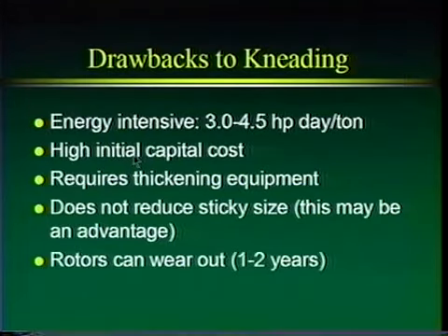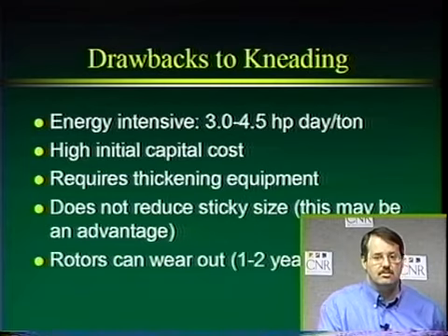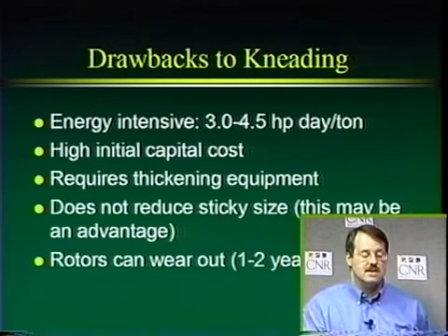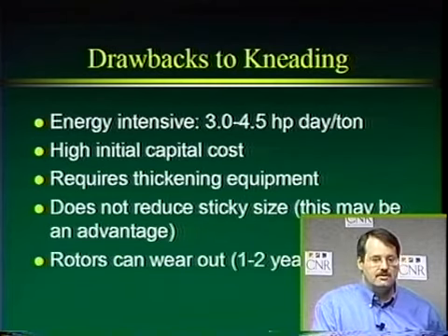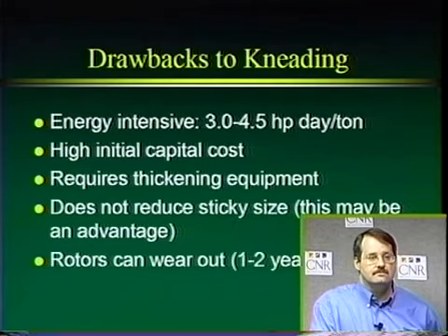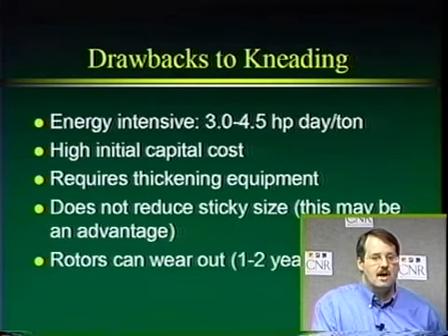Okay, so some drawbacks to kneading. It's pretty energy intensive, 3 to 4.5 horsepower days per ton. You don't run this unless there's a need. I'm very familiar with kneading of mixed office waste or printing and writing grades that are going to be recycled and used in copy paper.